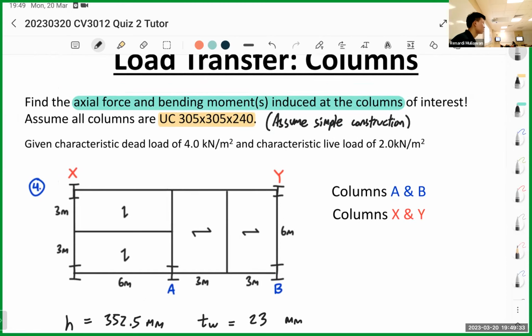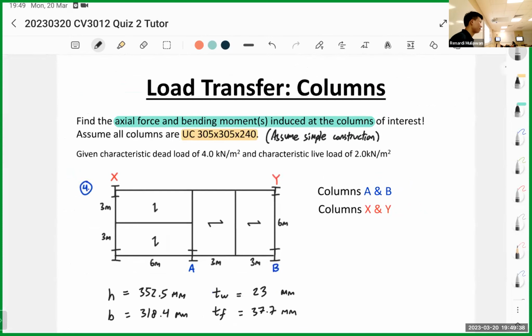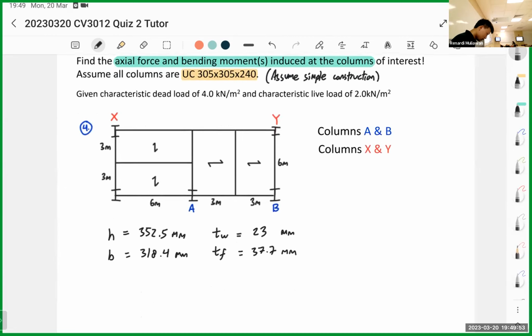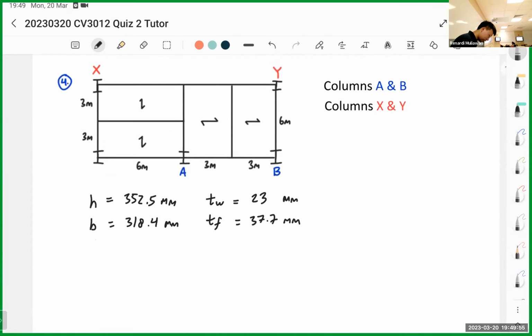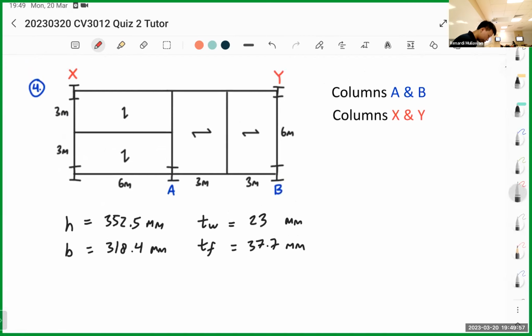Because if it's rigid construction, it's not easy to get the moment because you need to consider the eccentricity and also the bending moment. So the beams are rigid, and we're not going to touch that. That one is very complex. You need a program actually to do it. This one is all simply supported. Okay, so let's say we do column.